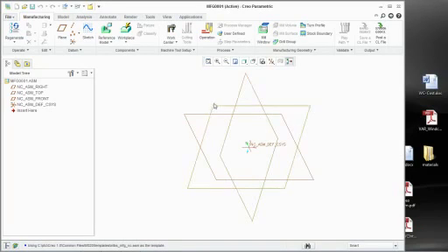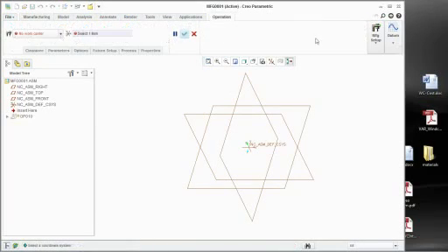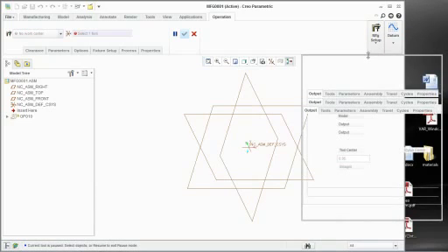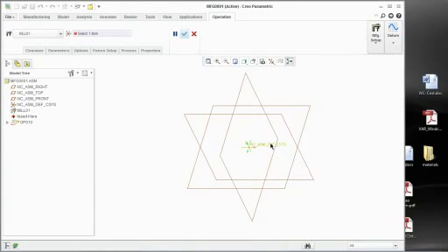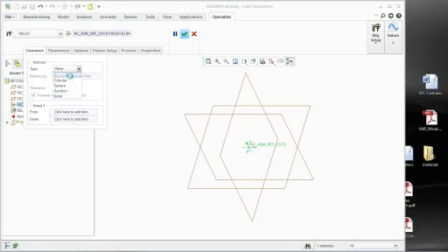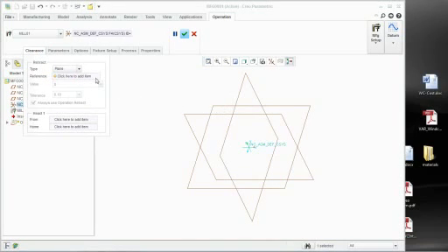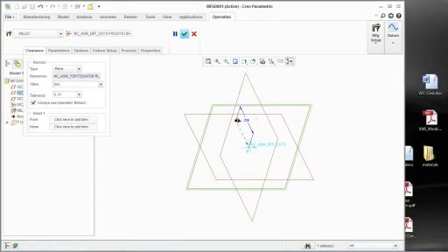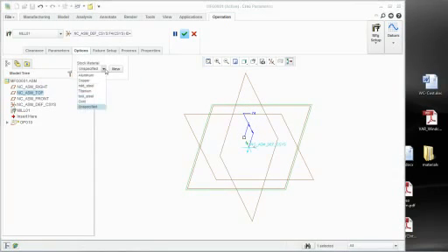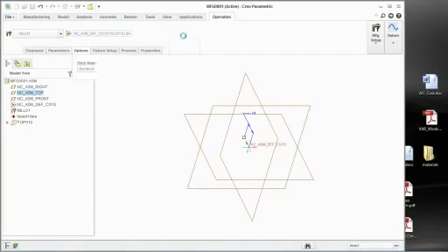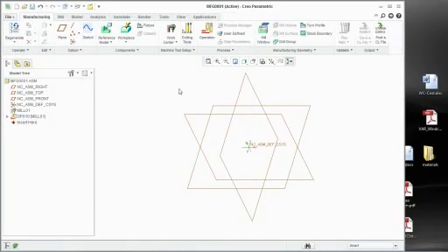And so a lot of times what you'll see are users come in, and every single time they get in, they're creating an operation, they're picking a machine that they're going to use, they're doing a lot of this button pick and click. They have to set their machine coordinate system, they have to set up their clearance plane. Okay, a lot of these different things that you come in here and you set up, and I've seen this done a number of different times. You're coming in here and you're pick and clicking, you're setting up your stock materials, and you're doing all that every single time. And then not until that point can they actually start machining.